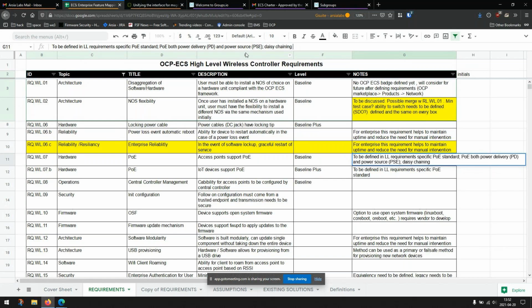So the latest spec is 802.3at. That was the PoE Plus version. Earlier was 802.3af, which was PoE. Right. And automobiles are looking at 2-wire PoE, which is a completely different power. So in a sense, AT is the widest. I mean, you're talking millions of ports per month.